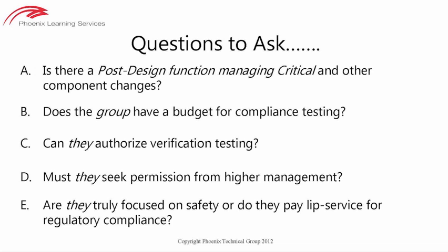To ensure ongoing compliance, here are a few questions to ask. Is there a post-design function managing critical and other component changes? If there isn't, then how do manufacturing and future manufacturing changes, component replacements, component obsolescence, how are these things going to be mapped back into the original compliance work which you did in design? Does the post-design function have a budget for compliance testing?